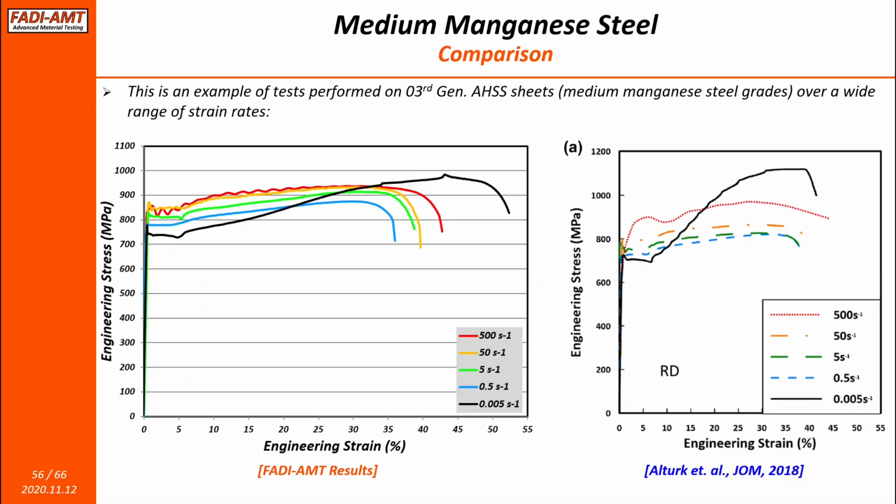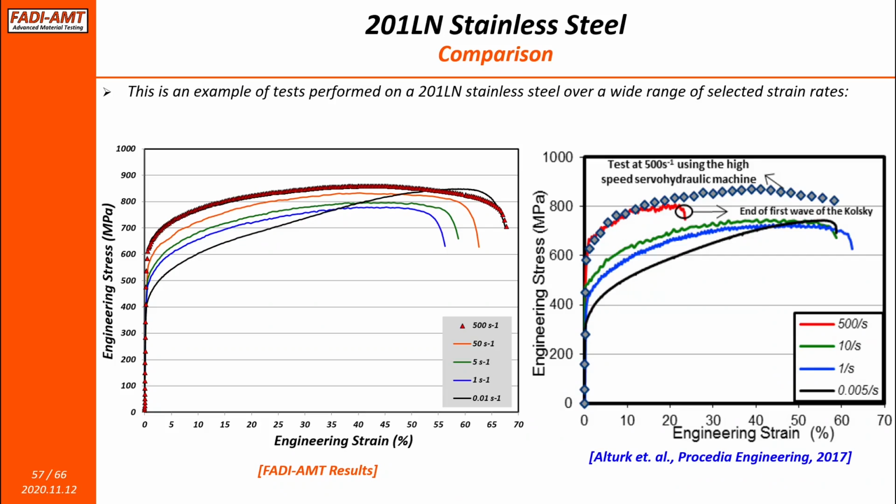From our humble experience, if we deal with materials that have a YPE, which clearly this material exhibits, even at quasi-static conditions, you can see it very clearly. We tend to notice this all the time. If we have a YPE, it is almost impossible to avoid those smaller fluctuations. They're not as large as ringing fluctuations or sort of waviness. So they will always be there. And we've learned to just accept them because that's the best that you can get with such materials.